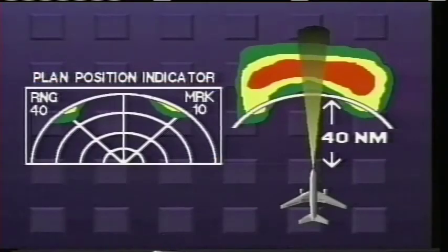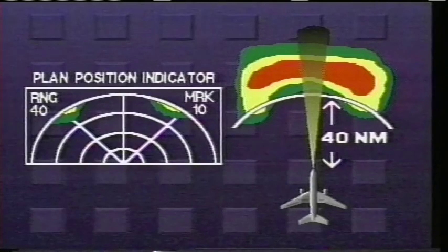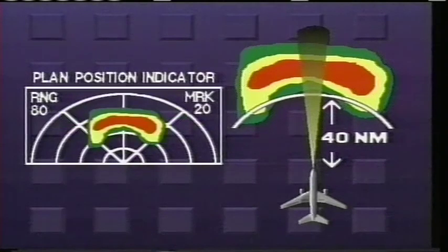A blind alley, or box canyon situation, can be a dangerous trap for pilots that habitually fly with the radar on a short range of 40 nautical miles or less. The short-range returns show a corridor between two areas of heavy rainfall. The long-range setting shows the trap. Always switch to the long range before entering such a tempting corridor.